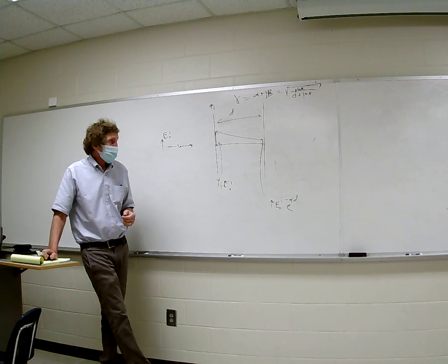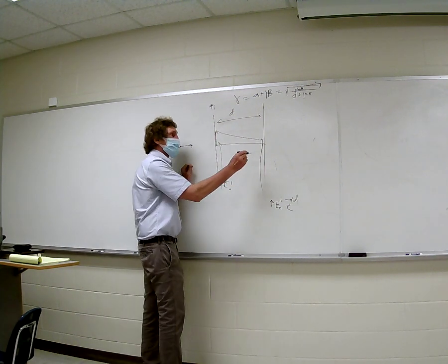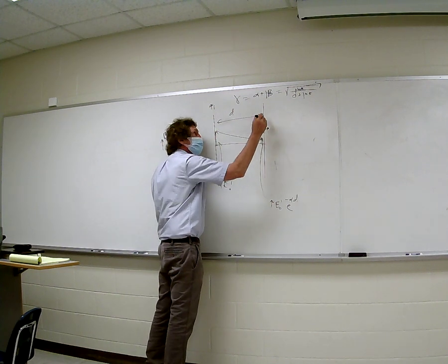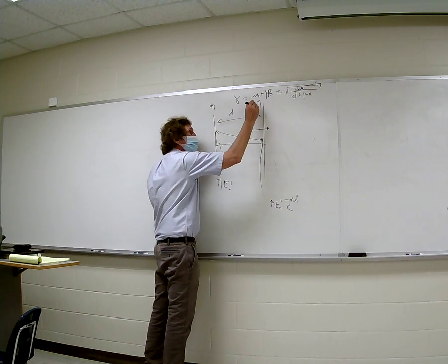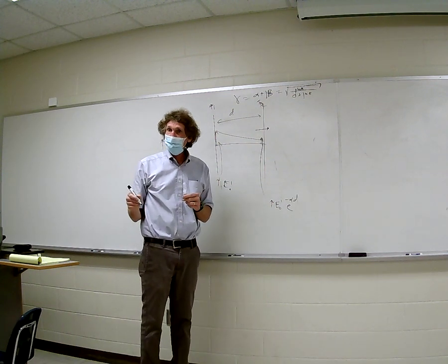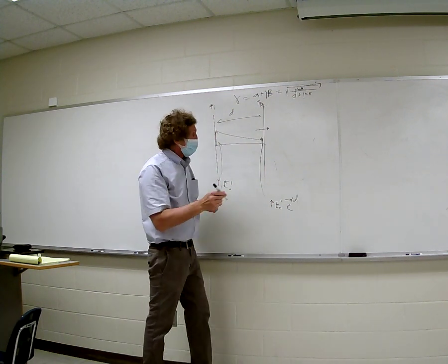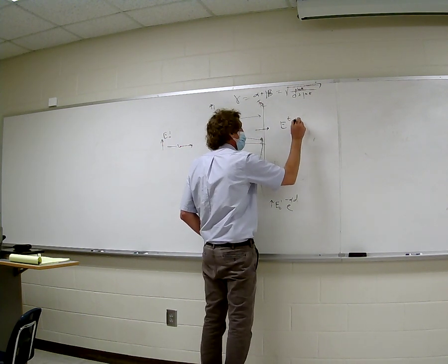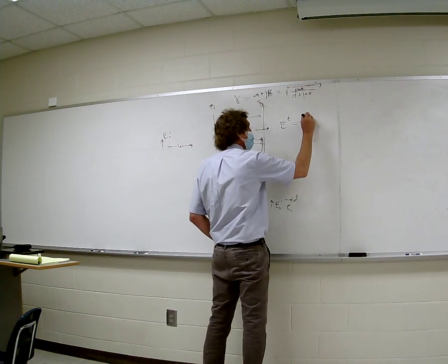All right. Now we're not quite done. That's the electric field strength just before you get out of the shield. Then you would have to multiply it by the transmission coefficient in region 2. Do you agree with me? Y'all remember doing this? And therefore, the actual transmitted field would be equal to the incident field strength times the transmission coefficients.